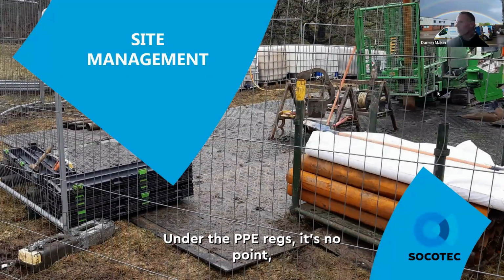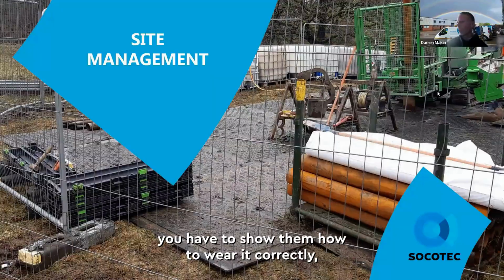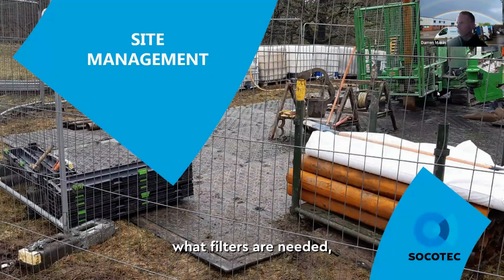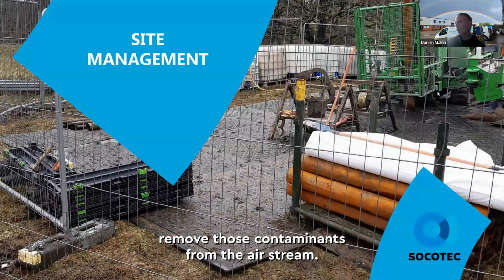Under the PPE regs, you have to give the training, so there's no point in giving somebody a respirator and saying, just wear that. You have to show them how to wear it correctly, what filters are needed, and why you need those filters to absorb and remove those contaminants from that airstream.